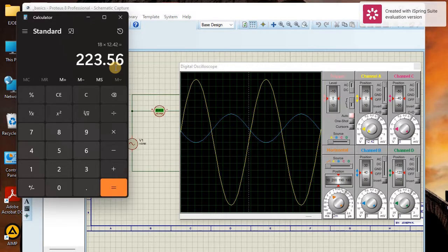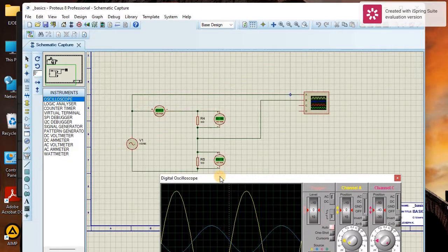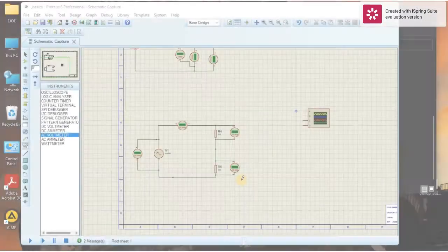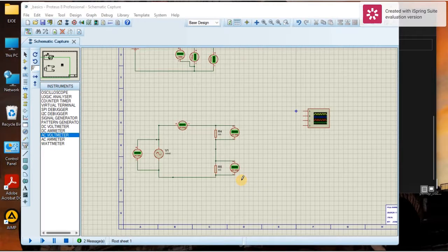This isn't right, I think. It isn't right. Yes, alright. So I figured out what the problem is, and it is because I forgot to ground. I forgot to add a ground here. So yeah, that is required if we are to get a proper AC signal.